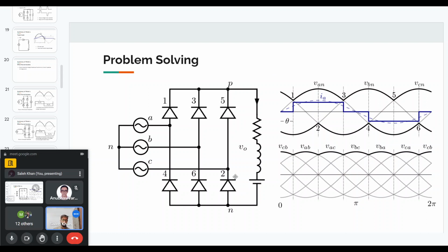So this is how the voltage develops at the output. And the E voltage should obviously be less than the voltage here. Since I mentioned that the 230 volts is the phase voltage, the line voltage, if you calculate 230 root 3, will be 400 volts RMS.